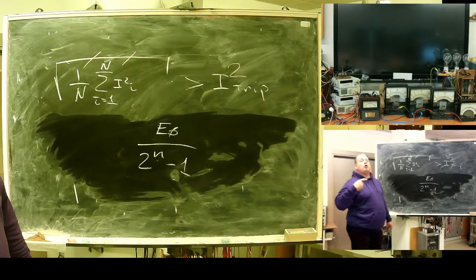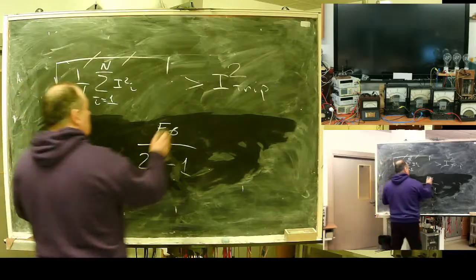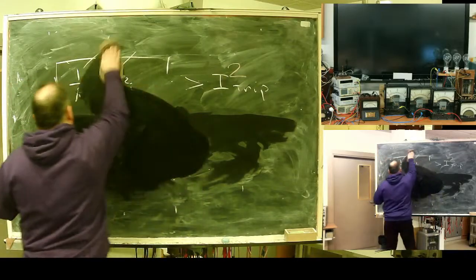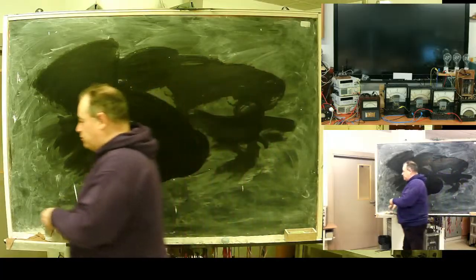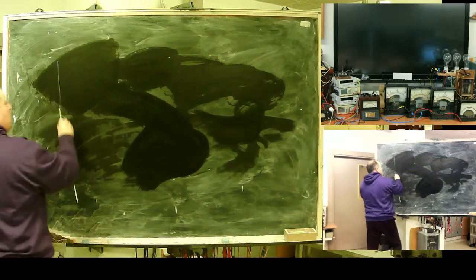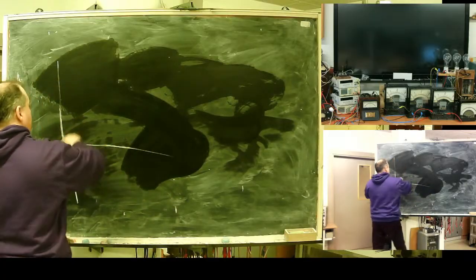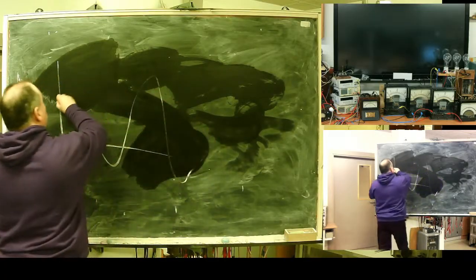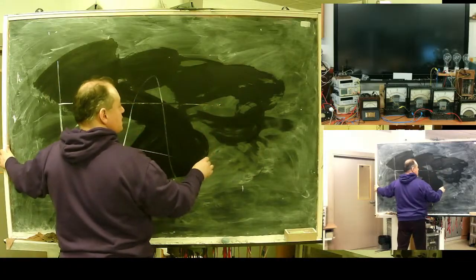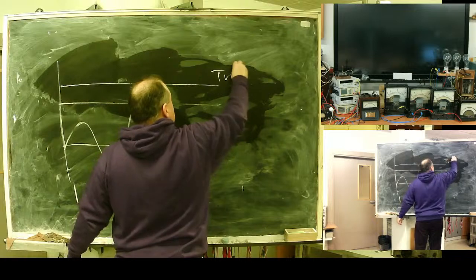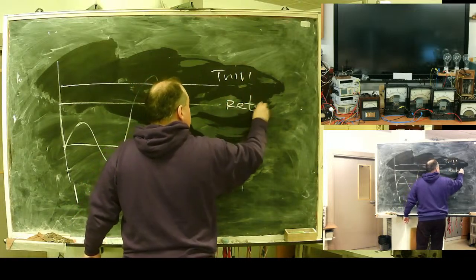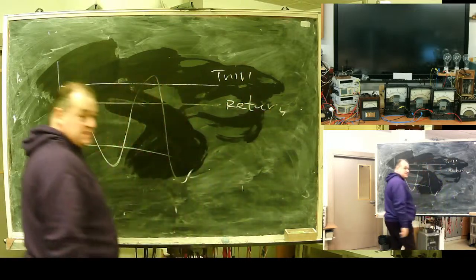Second, the signal itself is not stationary. What does it mean? To prevent multiple stupid trips, triple release, I need to have two thresholds. Understand?